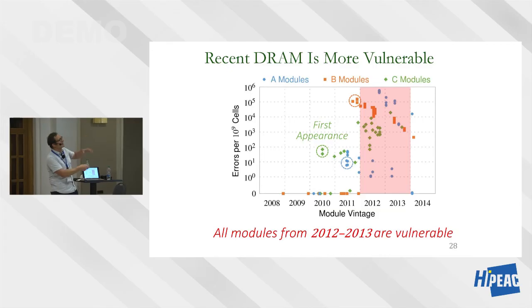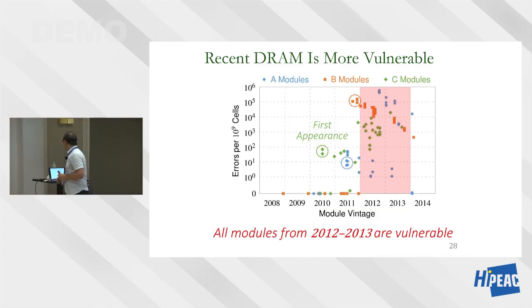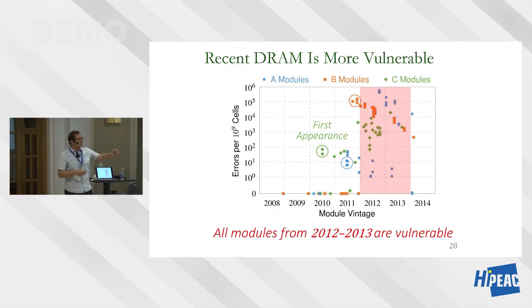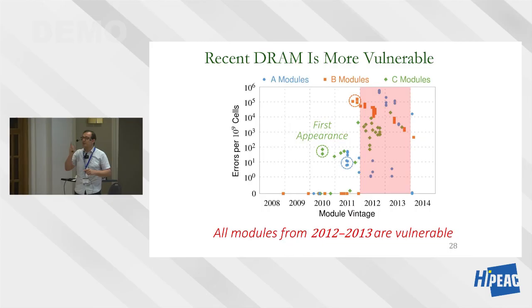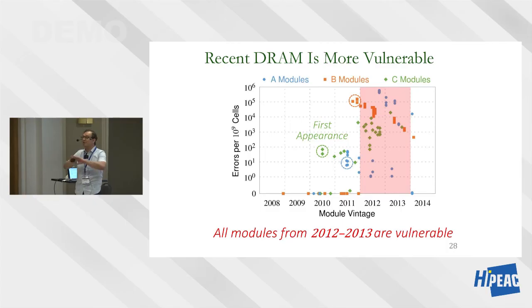Don't focus on the error rates. These change over time, etc. It depends on the testing, etc. But basically, we argued that this is a technology scaling problem, meaning that in the older DRAM chips, you cannot do enough hammerings to cause a bit flip, because cells get refreshed before you could do enough hammerings, because cells are far away from each other and cells are bigger.